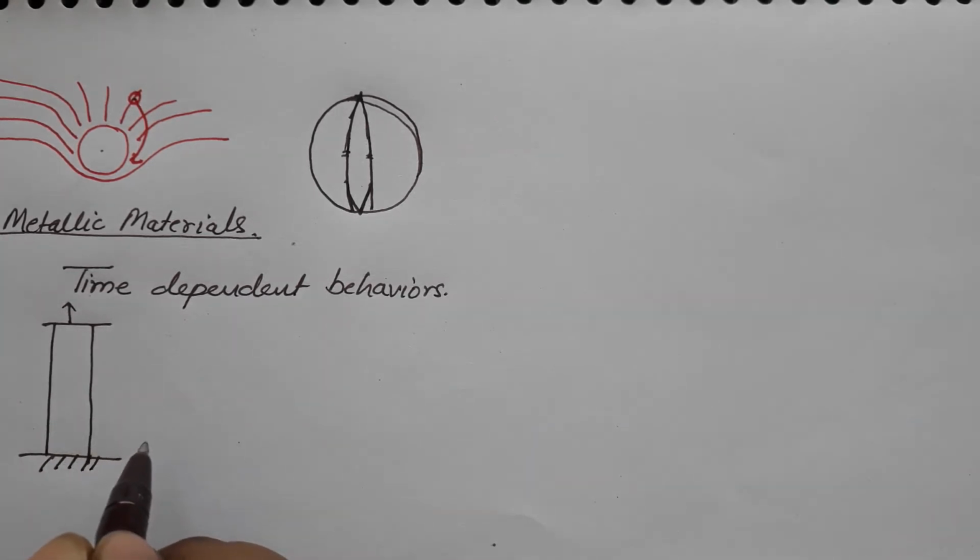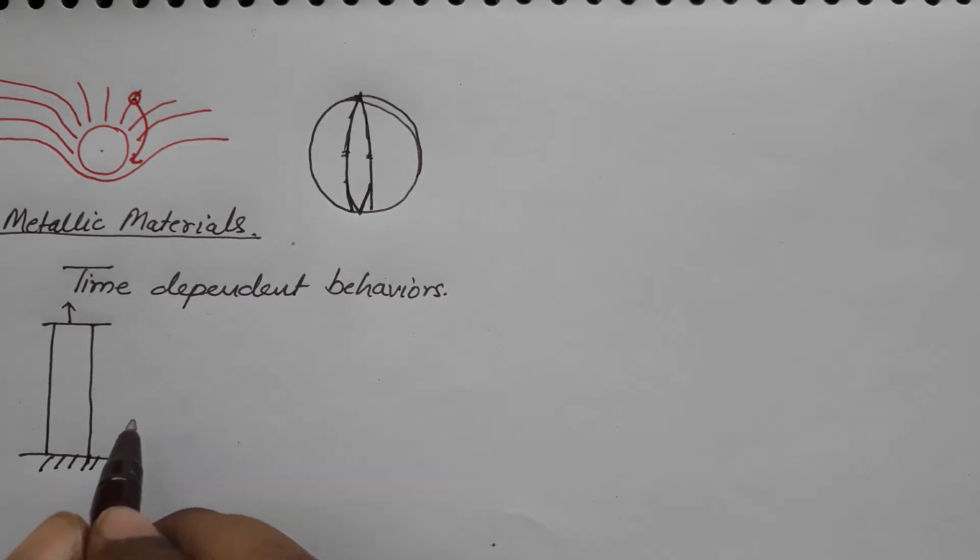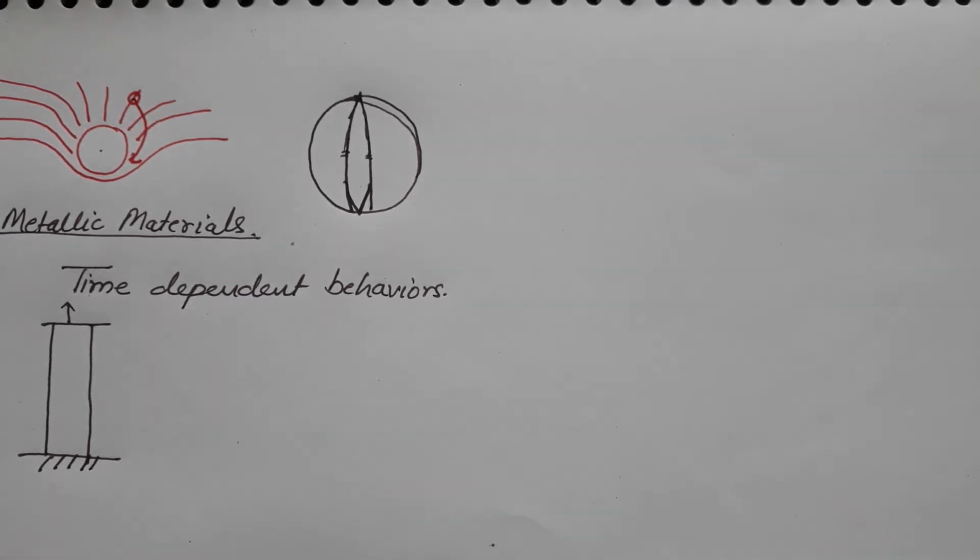If a liquid becomes very viscous, then you will see similar behavior to what happens in a solid. However, the difference would be if the solid becomes crystalline. If the solid becomes crystalline, you create more and more constraint on the way atoms can move, and that is the concept of dislocations, which we have touched briefly.